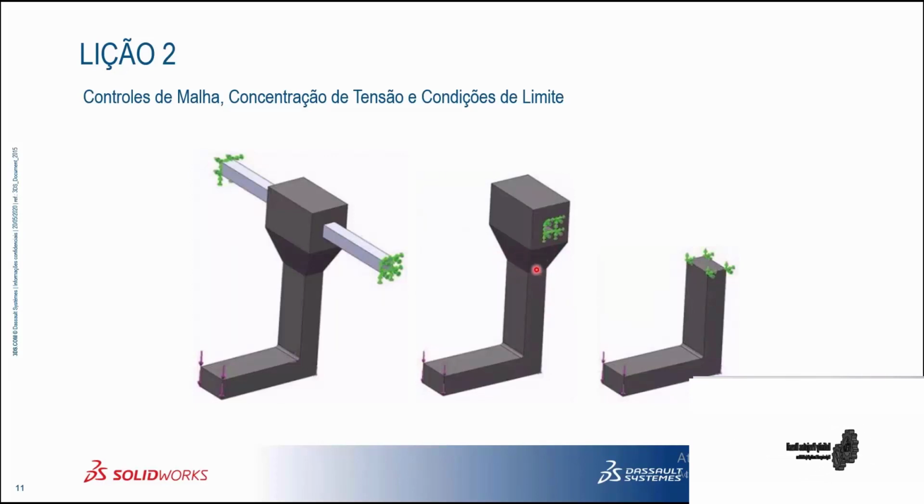In our case, I would like to know if this support would resist the force of a TV applied to it. Then I only took the support for resisting. If we wanted, for example, to know the breaking point of the weld in the connection of these two components, there are several cases that will depend on the type of result you want. In the previous case, the most precise option for the result would be a uniform mesh, without those new stress points up here, also with the simulation of the welded model itself. So we can see that it would be the most accurate.